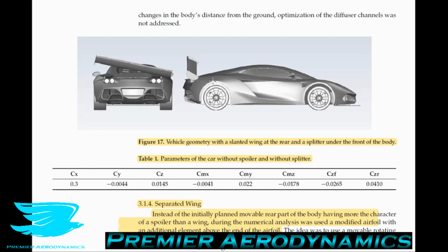If you look at a car, often they just look like flying wings. You can see here, the curve on top and the flat underbody is effectively just a cambered wing going along. That's going to be producing a lot of lift. The way that we get around that is by lowering the car to the surface, and we sort of restrict how much fluid is going in underneath.